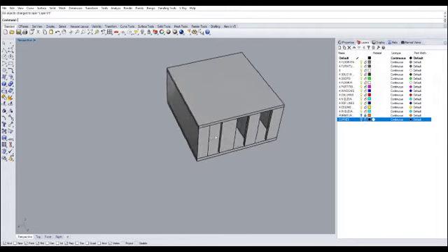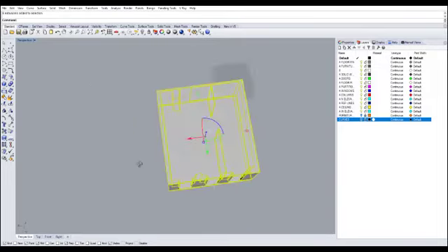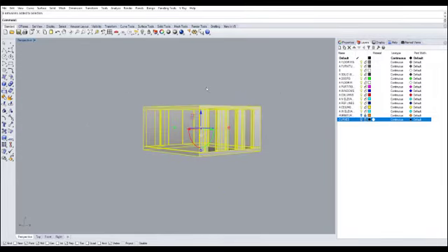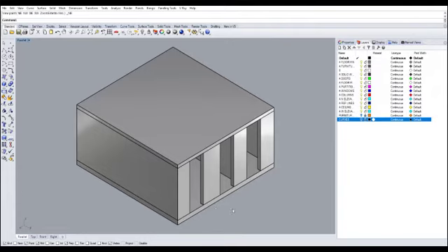So let's make sure, before we get to that isometric view, you have the model that you're trying to render into a 3D portrait selected entirely. Make sure it's selected entirely. And then I want you to go to the triangle arrow on the View tab. Go to Set View, go to Isometric View, and then click on Northeast. Notice after you've done that, your model has been centered nicely into the center. And then of course we have our isometric view, which is a slightly less restricted view than axonometric.